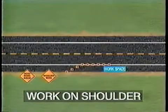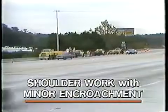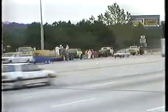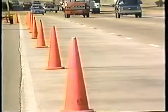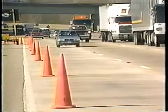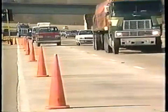A buffer space should be provided in advance of the workspace. When work is on the shoulder or takes up part of a lane, traffic volumes, types of traffic, this could be buses, trucks, and cars, speed and capacity should be analyzed to determine whether the affected lane should be closed. Now, the lane should not be reduced to less than 10 feet. You can consult Part 6 of the Manual on Uniform Traffic Control Devices.